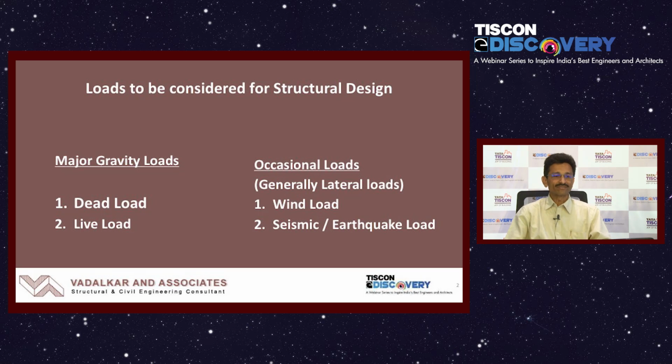Now generally, different types of loads are considered for structural design. The majority of the loads are gravity loads, mostly the dead loads and live loads. These are generally taken for design of the structure. But apart from that, there are other important loads like wind loads and earthquake or seismic loads. Those are also very, very important loads. Generally, they are lateral loads, while gravity loads are acting in a vertical direction. That is a major difference.